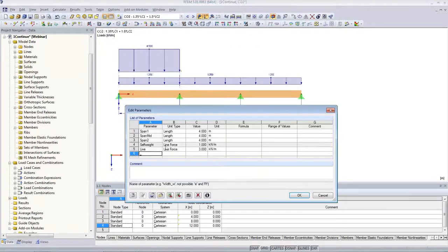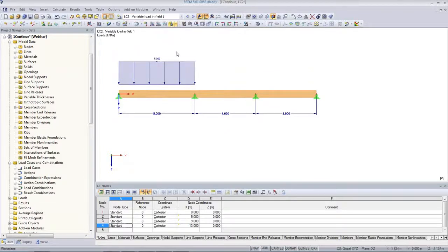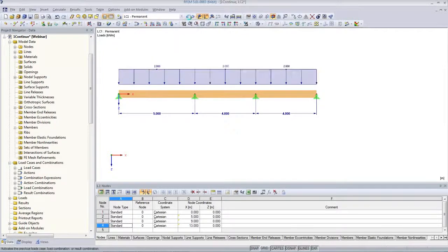See how it works? So 5, load case 2, load case 5. Okay. You see here it changed because in this combination we have 1.5 load case 2, so 5 times 1.5 is 7.5. If you want to see the real value, you go here and select the load cases without safety factors.